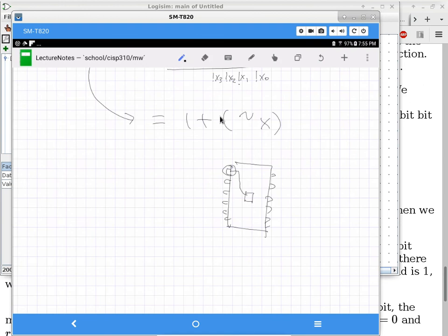Okay, then it depends on whether it's an OR gate or an AND gate, right? So if this is an AND gate, then you go like, well, I don't want this pin to really affect anything, so what value should you specify? A 1, exactly. So in general, you want to connect this to what we call the power, because power means 1. But this is also a bad idea.